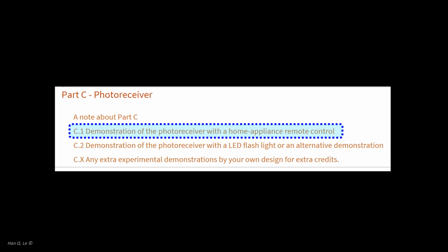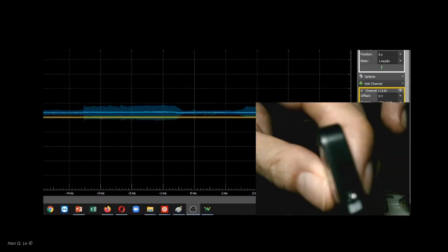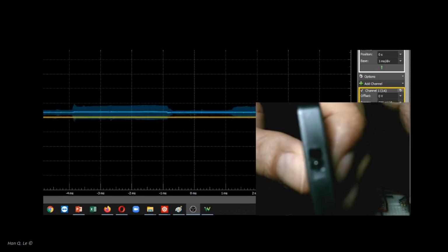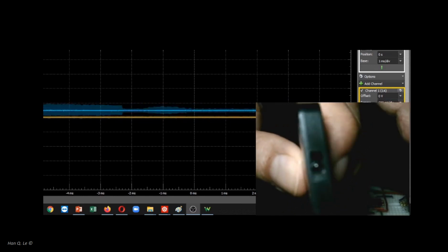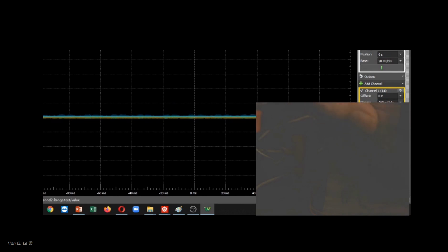The first test, as mentioned in the introduction, is a simple communication device, the remote control. The remote control light output can be seen with most cameras, unless they have infrared blocking filters. When the remote control light output is applied onto the photodiode, the signal may saturate the receiver, hence, adjust the remote control distance from the photodiode and the scope vertical scale to capture the signals without saturation or overscale.